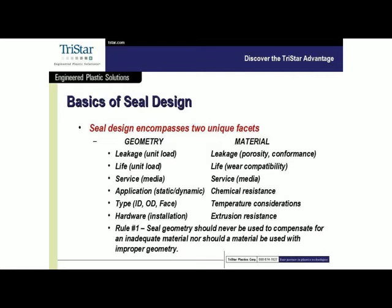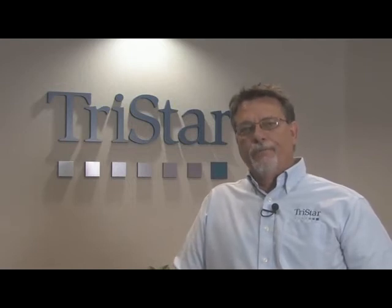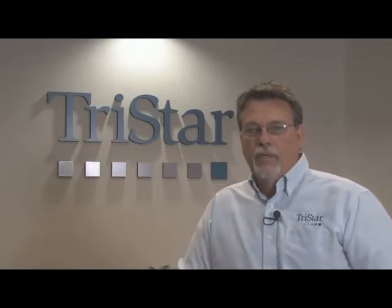Installation situation. Some seal geometries can't be used on some very small diameters, especially on small rod seals, for instance. If you have a very intricate geometry, when you go to try and fold that seal to pop it into place in a closed groove, you could deform it beyond its usability. So we have to be a little careful about the geometry and how it's going to be installed.